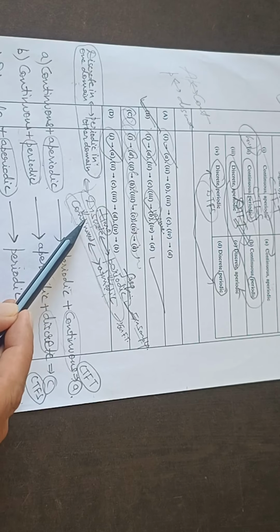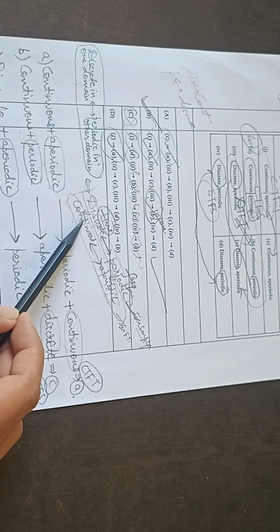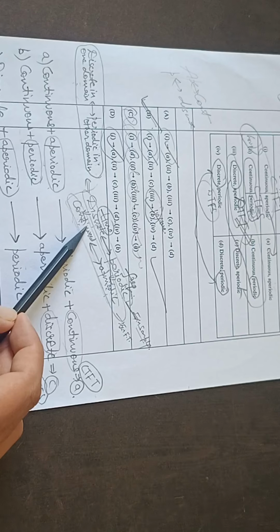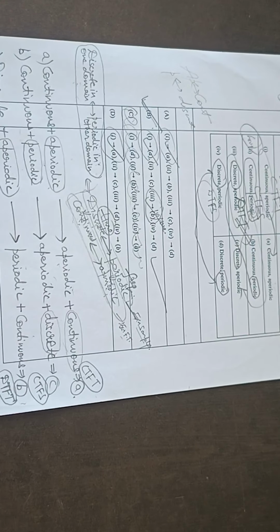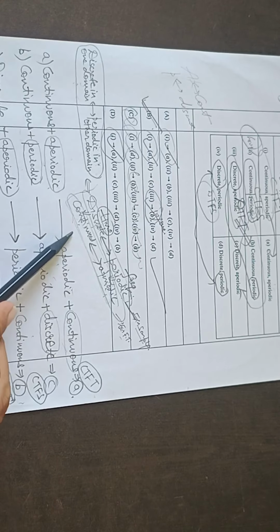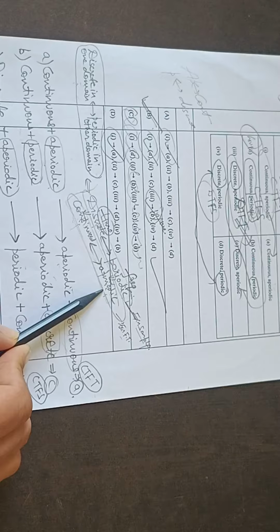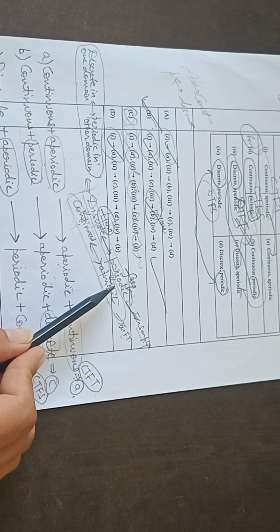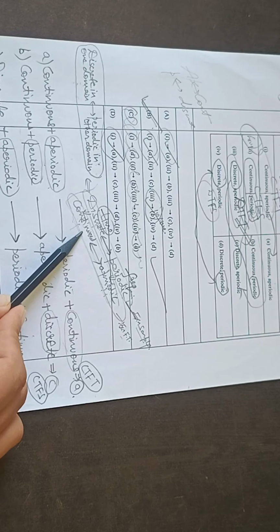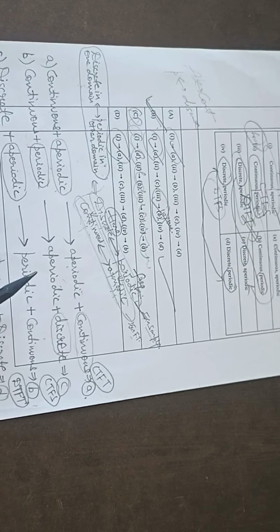If you take the opposite of this, the opposite of discrete is continuous. So continuous in one domain means aperiodic in the other domain. For example, Fourier transform. For Fourier transform, x(t) is continuous, so the spectrum is aperiodic. Similarly, aperiodic in the time domain means continuous in the frequency domain. These are valid both ways.